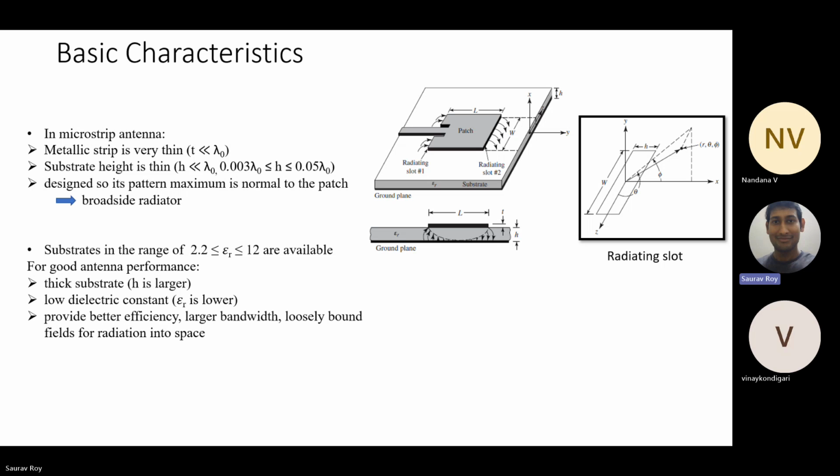You must see carefully what the length and width are, because all the other aspects of the antenna will depend on them, like the field modes, the electric field, magnetic field, and current density. The direction, or vector direction, of all the vector components will depend on this.